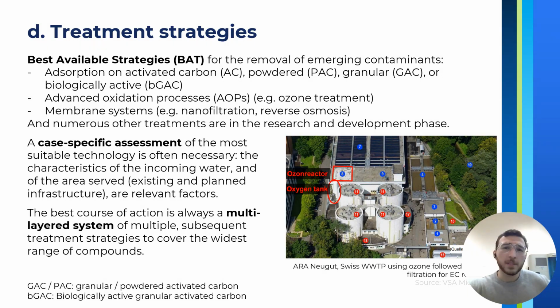So, we left off by saying that the currently best available technologies, or BATs, for the removal of emerging contaminants are adsorption onto activated carbon, advanced oxidation processes such as ozone treatment, and membrane systems such as reverse osmosis. Nonetheless, we also highlighted the need for a case-specific assessment of the most suitable technology to be applied in any given case. Differences in the incoming water or the existing and planned infrastructures are among the factors that may favor a technique over the others.